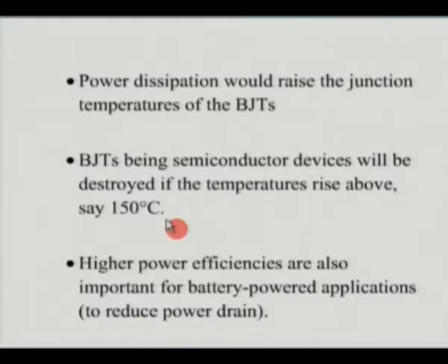It is completely useless. In fact it may not be a bad idea to just touch the body of one of these power transistors, which you would find on the bottom, or the rear side, of a public address system, or sometimes even in power supplies. It is a good idea to just touch it. You will always see it will be warm, and we are talking about 150 degrees, which is very, very high. So we need to ensure that the BJT junction temperature does not increase, and it is kept as close as possible to the ambient temperature.